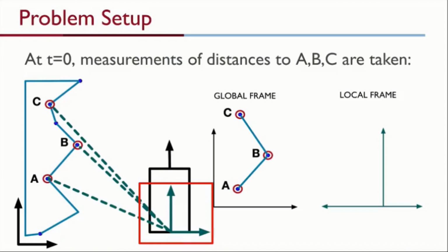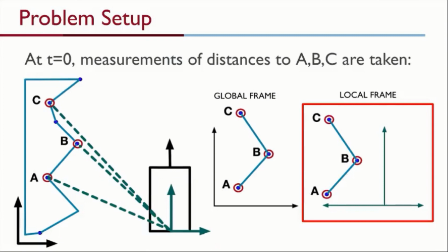The robot itself has its own local frame of reference, where we place the origin of the reference at the center line between the two rear points of the body. In the F110 car, this would be the center of the axis connecting the two rear wheel tires.